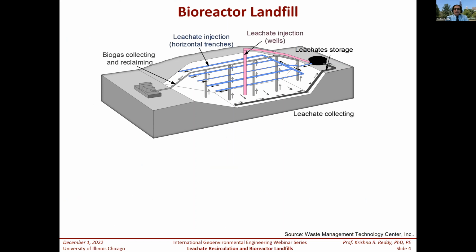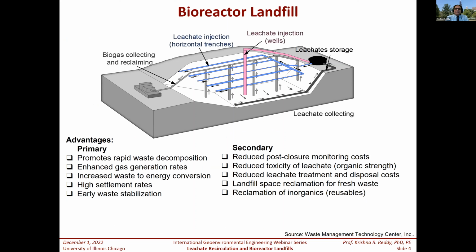So what is this bioreactor landfill? A bioreactor landfill is basically the same as a Subtitle D landfill. So you have this bottom liner, you have a leachate collection system, you have a final cover. So everything is as we are doing, okay? The only thing is, right now we are basically taking out the leachate and treating it on site, and disposing of the treated water into the surface waters, or taking it to a wastewater treatment plant and treating it.